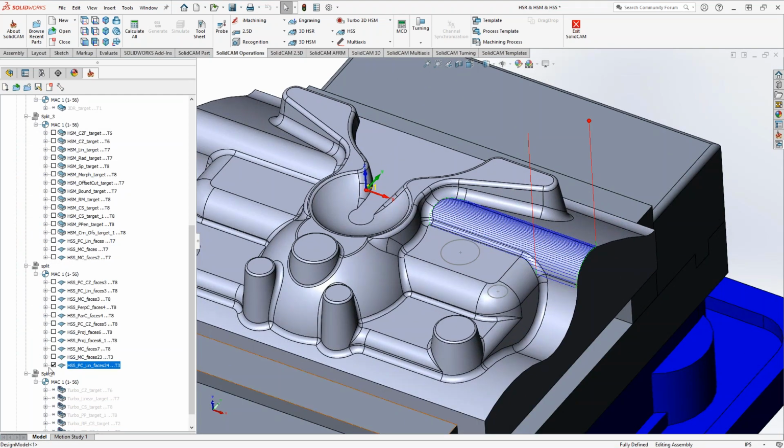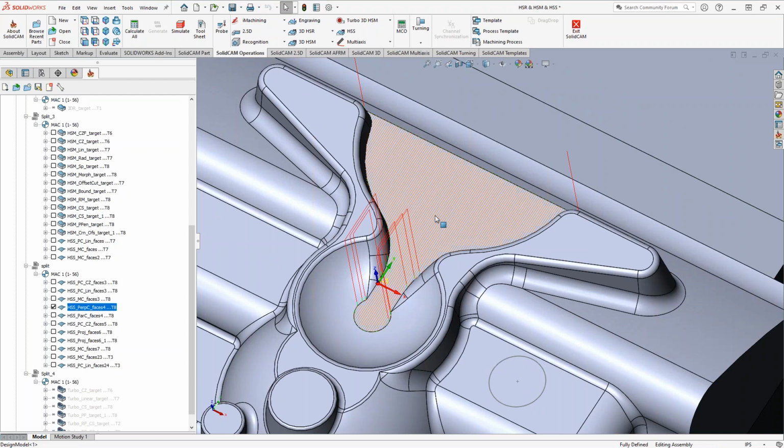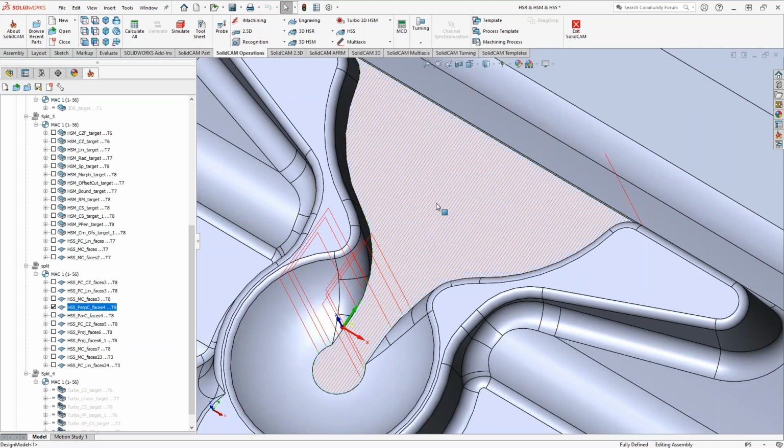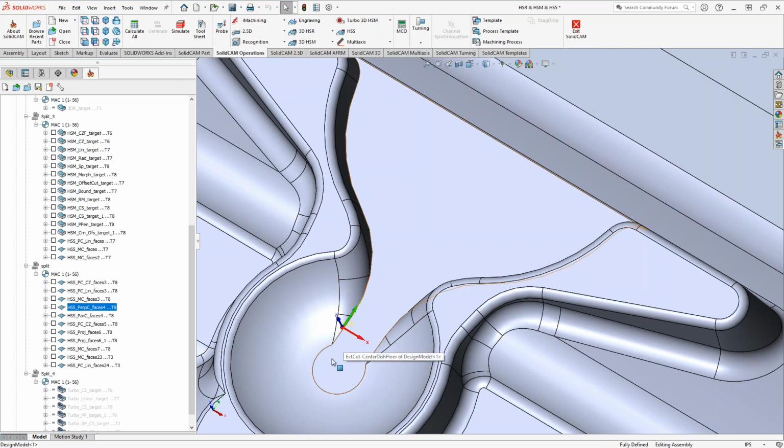So let's say if we take a look at how I've done a lot of these examples here. Maybe not these first three. Let's go to this one here. If I look at this little bell shape on the back here, I would stick with something like linear or perpendicular to curve like I've done here, because it's a nice flat surface. There's no need for me to really change too much direction, especially if you consider that if I did change direction, if I did maybe parallel to curve, it's going to collapse the toolpath here, and I'm not going to get a nice smooth looking toolpath.